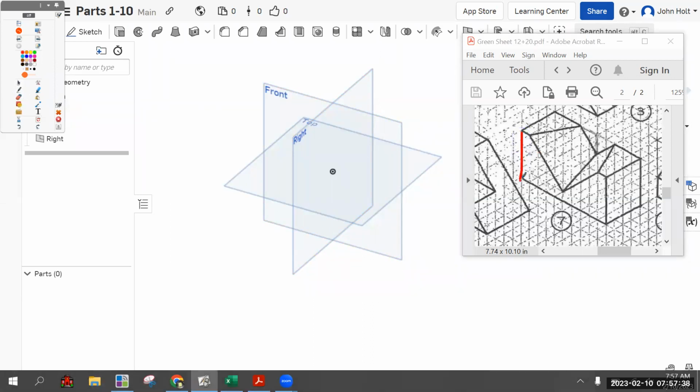One of the sketches is going to be the front, which looks a lot like part J on the other side. And then the other sketch is going to be the back, which we can presume goes like that, sort of towards the back, even though we can't see those back bottom edges. And then once we have these 2 sketches that are on different planes, 4 inches apart, we can loft one into the other.